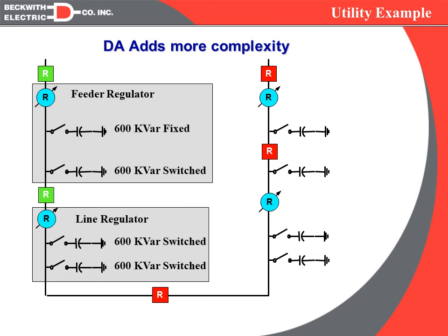So you can see that if we do the distribution automation and the automatic switching of circuits, we are going to have coordination issues with our time delays on both the regulators and the capacitor banks.